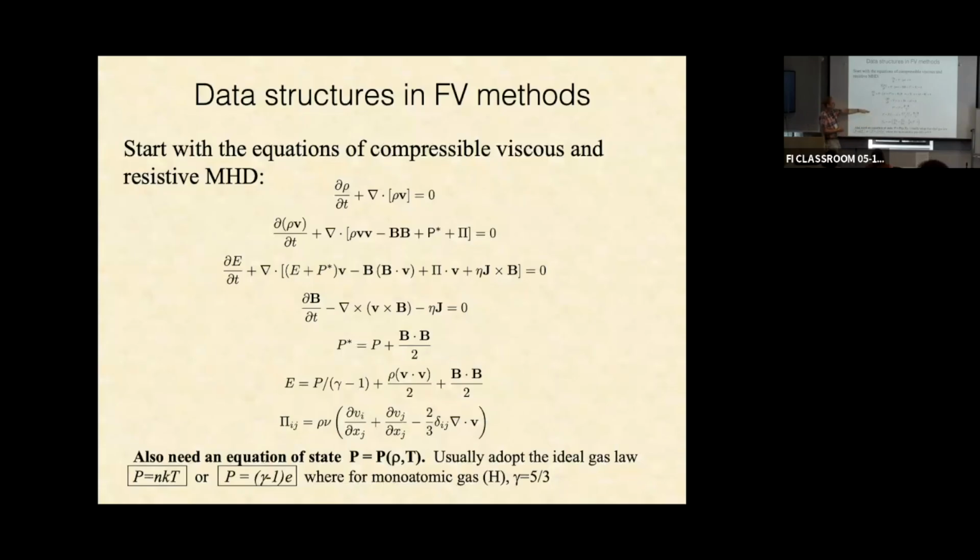So basically, these four equations are the evolutionary equations. And the things you need to store are the density, 3 components of the momentum, and the total energy. Those are the fluid dynamical variables. So basically 5 3D quantities, if you're solving 3D problems.